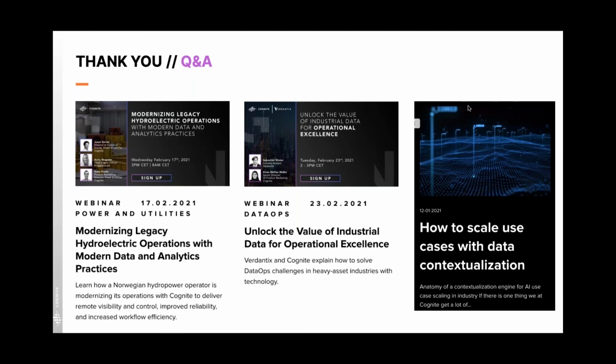There we essentially used physics model runs to build input to a simpler model, which can be executed very fast on dynamically changing conditions and produce a maximum capacity for a piece of equipment based on actual conditions and not conservatively set worst-case estimates, thereby increasing production in the entire facility by a few percent.